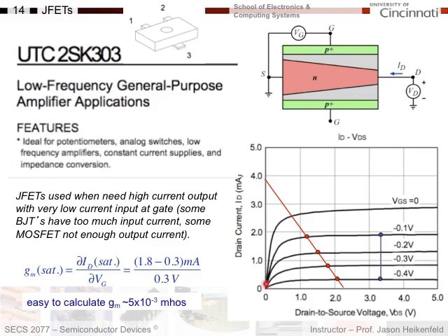Here's, off the spec sheet, the drain current versus drain to source voltage for a couple of gate to source voltages applied. We can calculate the transconductance. I have a load line plot here as well to help me out that I took from the spec sheet. Let's say I change my voltage from 0.1 to 0.4 volts. So that's a difference of 0.3 volts. That's my change in gate voltage, dV.